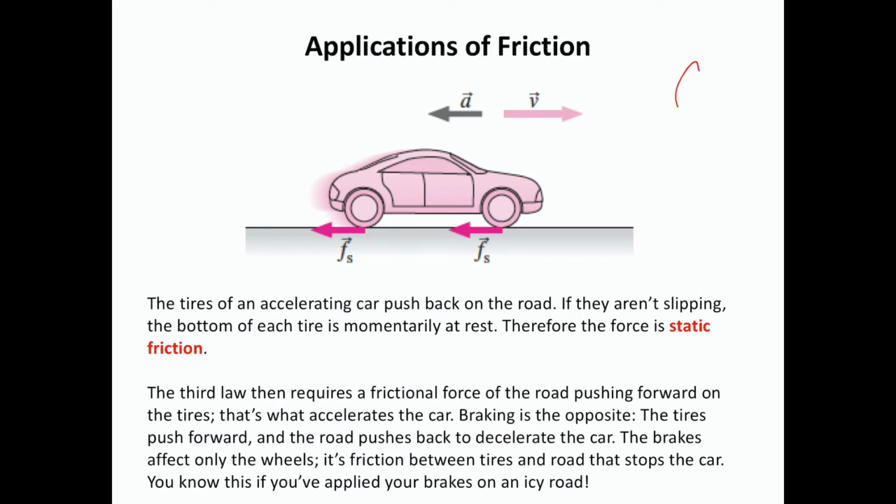Therefore, all the tires, if you look at Formula One, when they start the racing, do you notice what happened to Formula One? Before they really start, they have a warm-up lap. Exactly. They want to make their tires hot. Therefore, they sort of melt, not fully melt, of course. They calculated how much temperature. They sort of melt a little bit of the rubber with the road. So the road is very rough. So if you can melt a little bit, you produce more friction. So you say, why do they need friction? Later you will know.